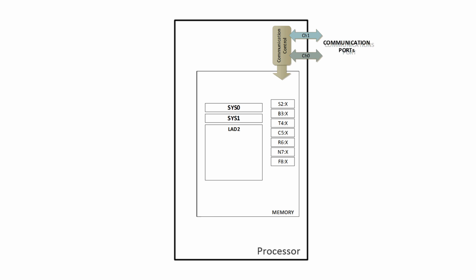That's where we'll just say your timers are. C for counters, R for control words. So T4, C5, R6, each one of those elements is made up of 3 integers. N7, the N implies integer, and so that's an array of 16-bit integers. But you can use the bits. You can use the individual bits in N7 or B3 exactly the same. And then F8, floating point.